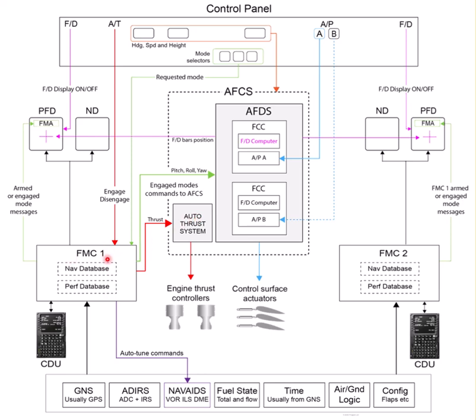So this is where the FMC starts to come in, because I've put information into the FMC. It knows the performance of the aircraft, it knows my weights, it knows the temperature outside. I've given it all the information necessary. So the FMC is going to send a setting out to the auto thrust system, and of course it's also going to set the bugs on the engine indication system, so the EICAS or ECAM. There's going to be a green bug showing me where the thrust is going to go to when I ask the auto thrust system for that.